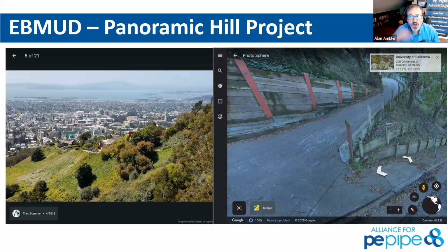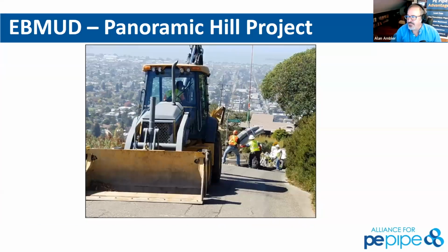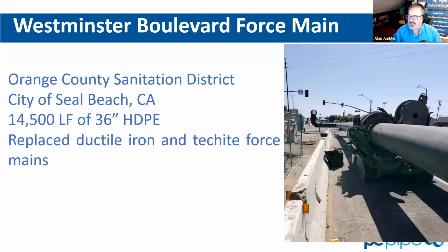East Bay MUD wanted to use high density polyethylene to push it through its paces to be able to test all of the allowable bending radius and confirm what the industry had said through this process, as you're seeing. And I will fast forward to the end of the story and say that they did confirm the table of allowable bending radius that the industry has pulled together for HDPE through this extremely complicated job as they moved through that and tested itself.